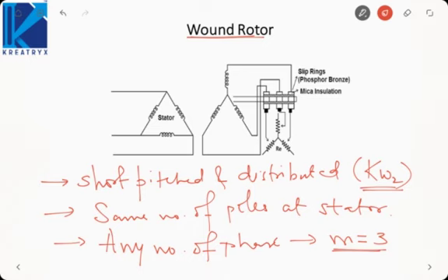That is, there will be harmonic torques produced in the rotor. So good mechanical balance is necessary since the rotor has to rotate. So that's why 3 phase is only preferred. And as you can see in the figure, the wound rotor always has the rotor winding in star.